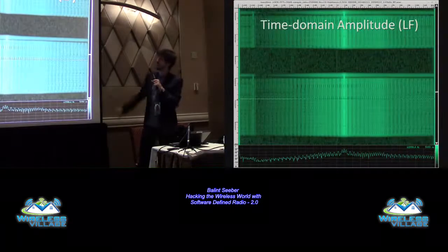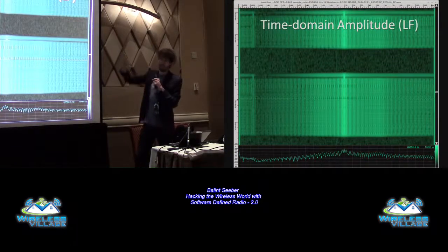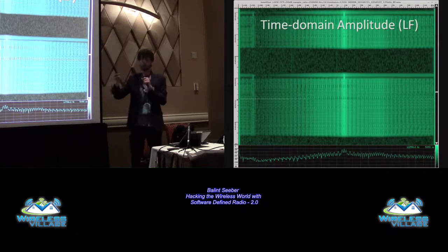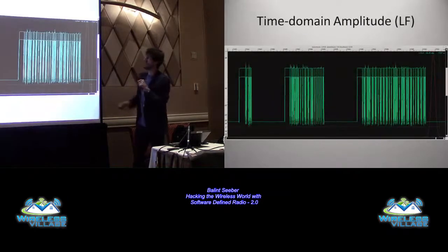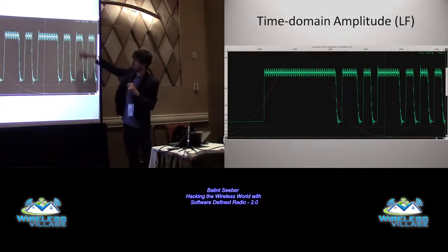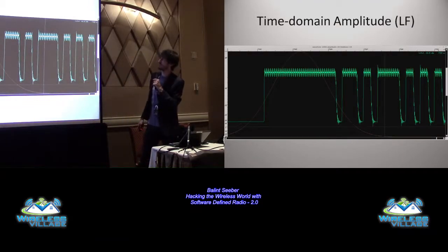And this is neat. This is the time domain of the LF portion. So this is the car constantly sending out things. Is anybody there? You know, is my real owner there? Again, you can see the pulses. You can decode that. Zooming in there, it's pretty obvious that you can turn that into zeros and ones.